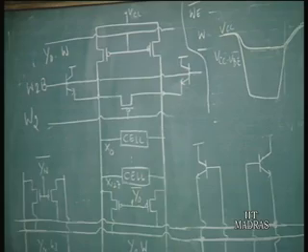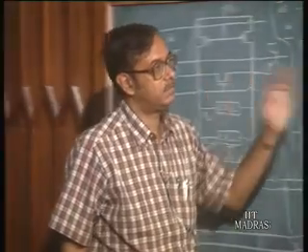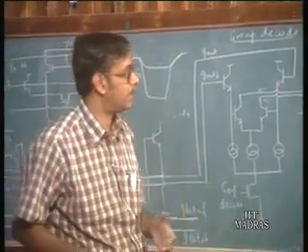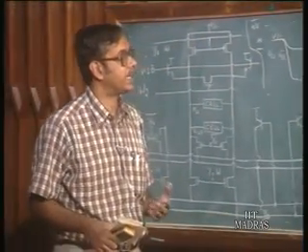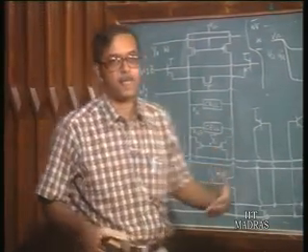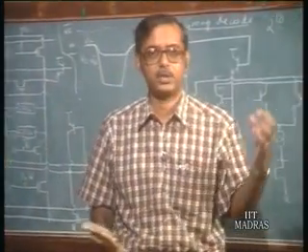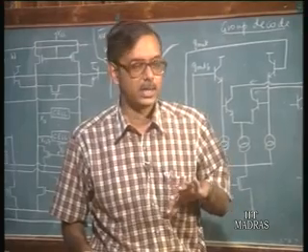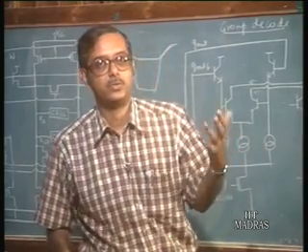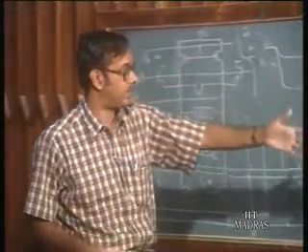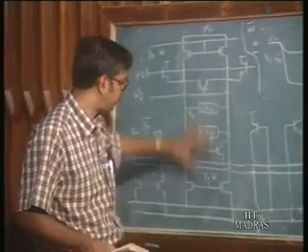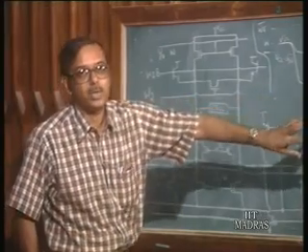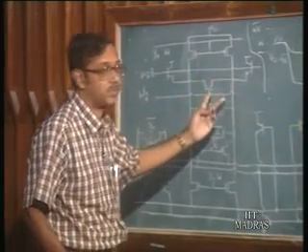Okay. So, this is how, just to give you a flavor of the type of circuit used in BiCMOS static RAM. So, you have first an ECL input, which is converted to BiCMOS levels basically, although the voltage levels are negative. Then with that you select a particular cell. In this case, you have a 3-level decoding, and then the sensing is done by bipolar differential.